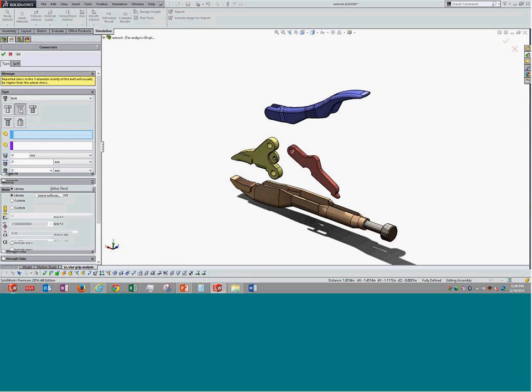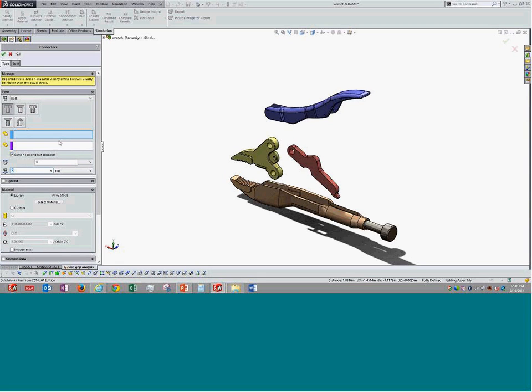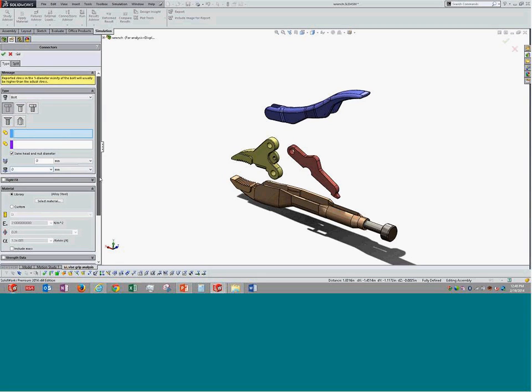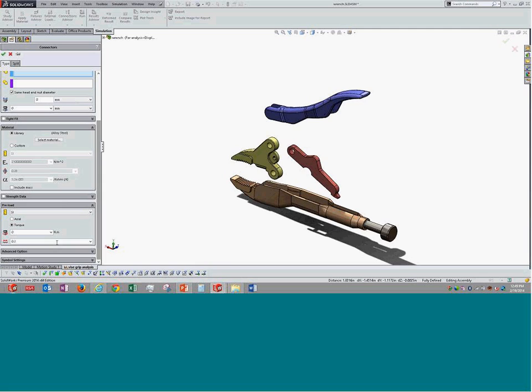You can select whichever bolt is going to act. Surfaces have to be selected. We have the option of tight fit, which will, if at all there is a gap and threading happens inside at a certain location, we can select it and select the appropriate pieces, or we can say tight fit and say that the threading is present all over. Multi remains as we discussed before. It also has the option of giving the torque and axial forces installed directly.